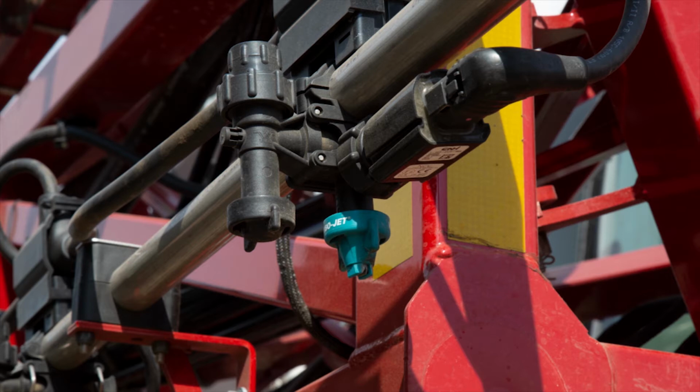The other thing to keep in mind here is being able to control a single nozzle versus a dual nozzle setup. On the Deere side, we do have the option to switch between nozzles automatically or manually from the cab without having to actually get out and rotate our turret. If you look at this particular setup, if we wanted to change nozzles, we have to come out, take this nozzle off, and put a new nozzle back on.